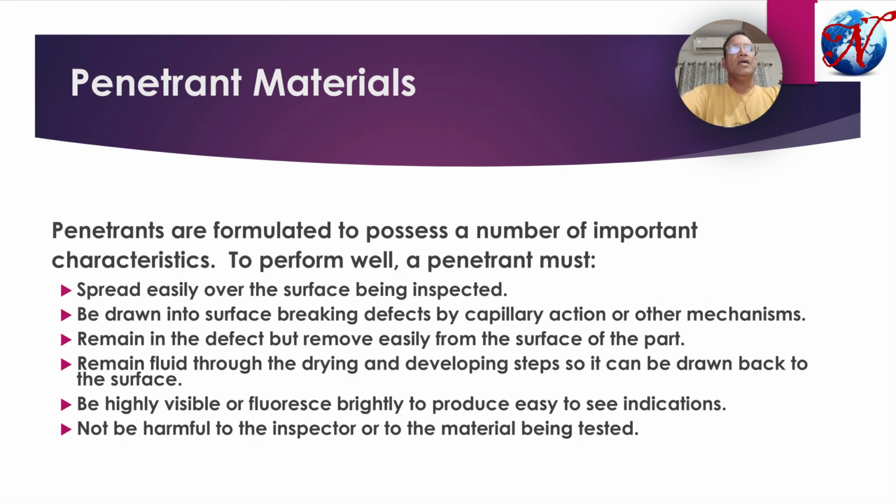The name of the testing implies that it is known as a liquid penetrant test. So here there are two terms, one is liquid and another is penetrant. We cannot say that every liquid is a penetrant. Penetrant means it has some penetration ability, and the penetration ability is developed in liquids which bear some specific characters. What are the characters? The first character is that the liquid shall have a tendency to spread easily over the inspection surface, and it is only possible if its surface tension is low.